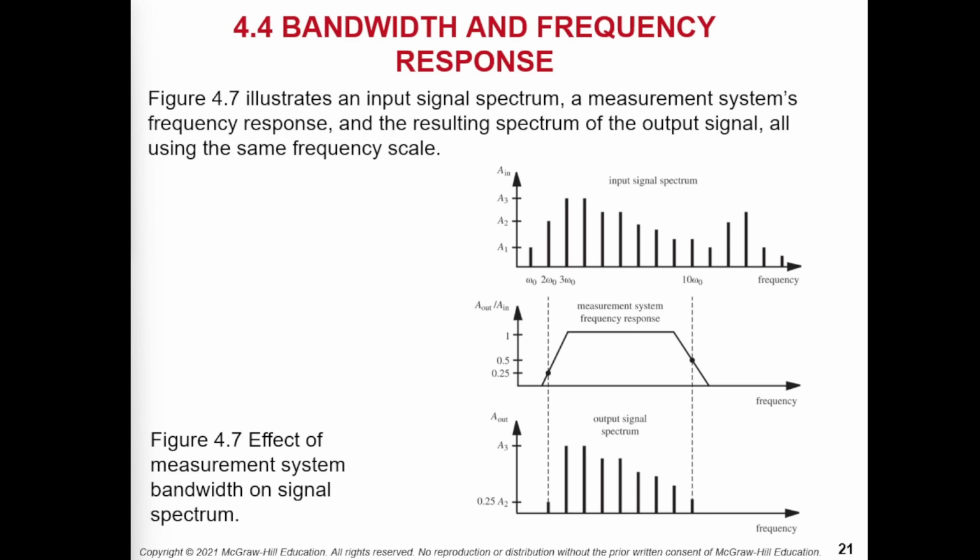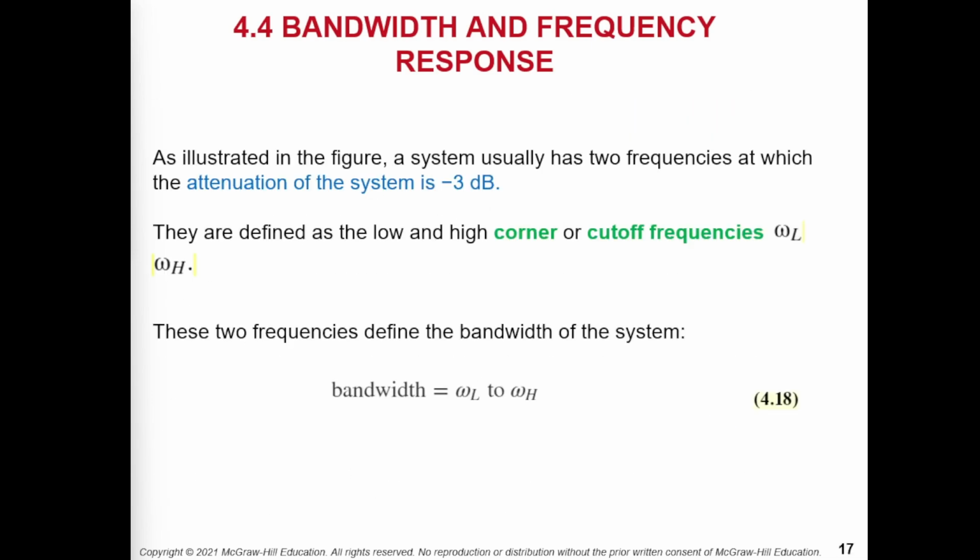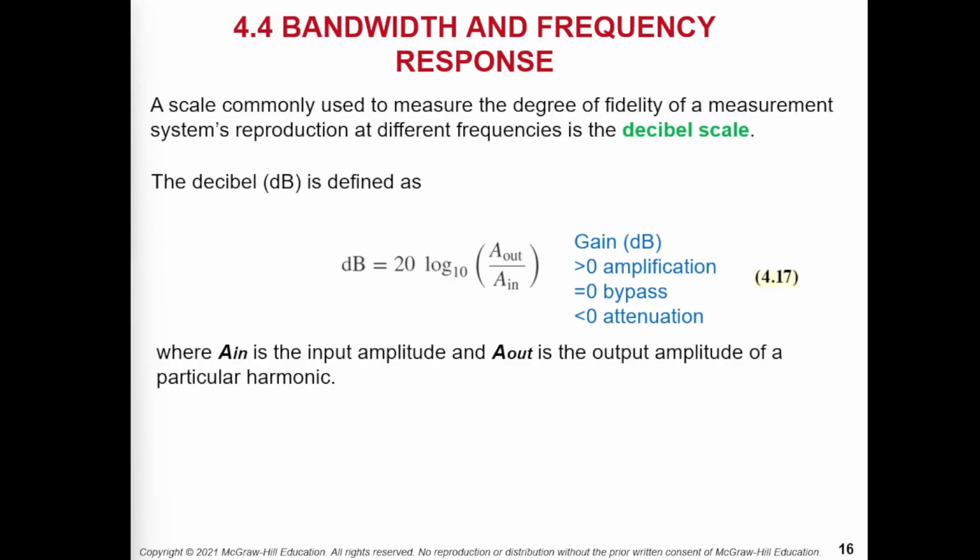After we know the minus 3 dB line, we can get a corner frequency. But how do we get a final response? After we apply the filter to the original signal, we need to calculate the ratio. So for the amplification factor, even though sometimes it's attenuation, sometimes it's bypass. Remember? We talked about this. This is the factor, or the ratio.